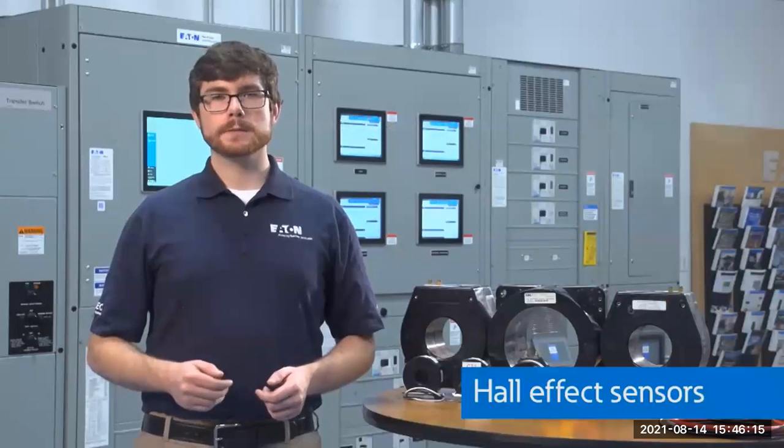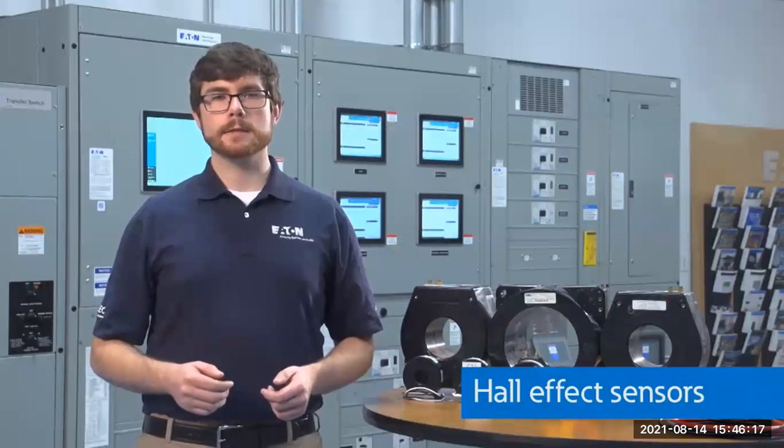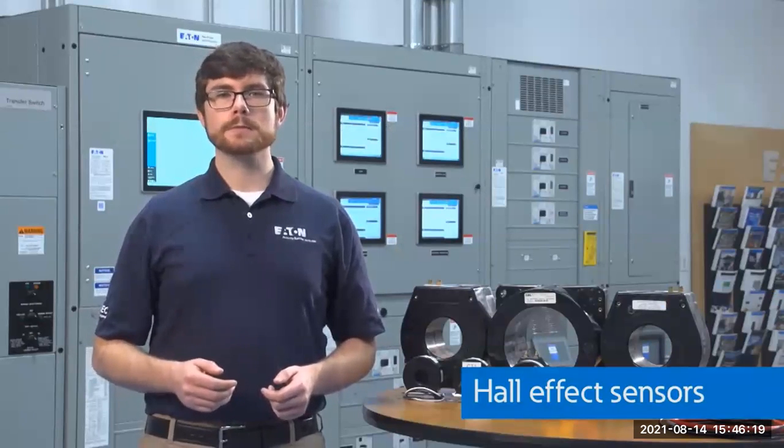This method can be used to measure both AC and DC current. However, as the current that is being measured increases, implementing this method requires the use of large, high current rated, and low ohmic value resistors that requires making a break in the circuit and adds an additional electrical component to the system. Just as shunt resistors can measure both AC and DC current, Hall effect sensors can also measure AC or DC current.